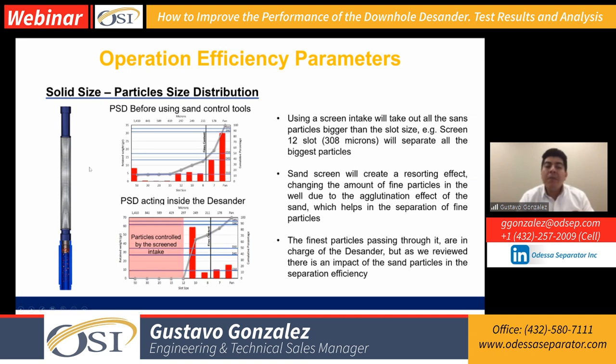So when the fluid passed through the screen, the linear velocity inside, when it was passing through the vanes of the helix, was creating a previous acceleration to increase that centrifugal force and create a better filtration. So that's one of the reasons that this type of configuration is getting a little more popular, for the benefit that we get through the system, creating those 2 stages.